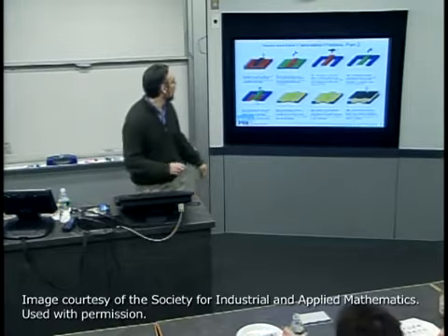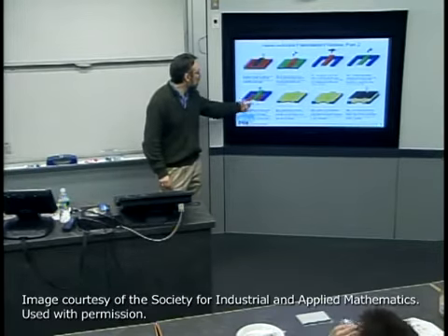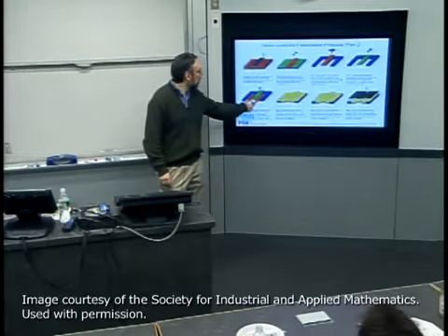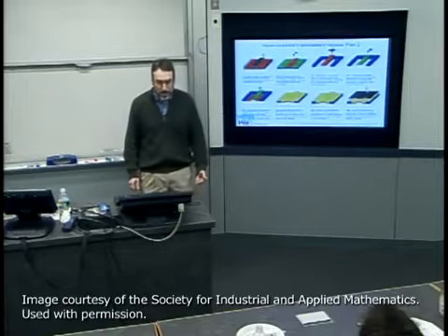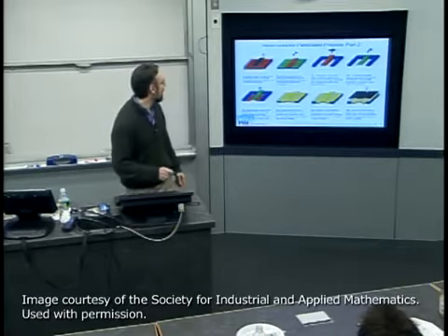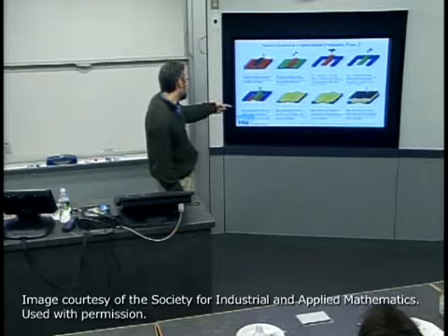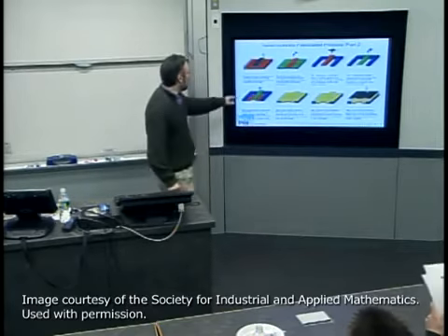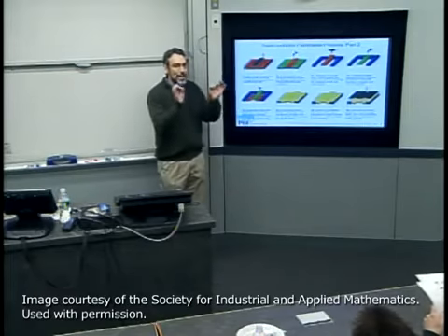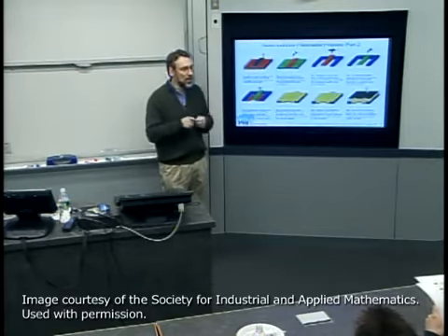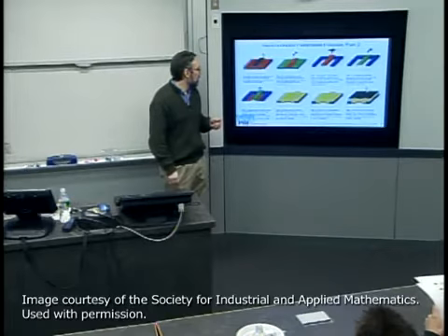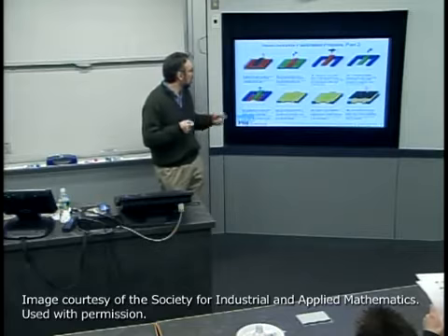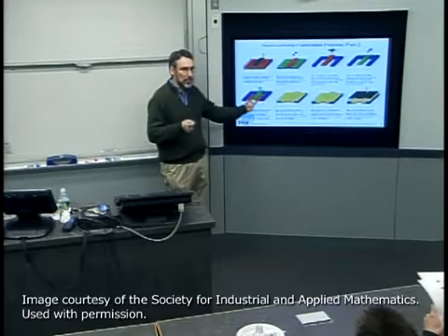Going on, the next thing we need to do is start to form these source and drain regions. We need to differentiate the silicon underneath. And what we're going to do here is use another process, an ion implantation process, I believe. Yes, I think that's what their little picture there is, where we actually implant those dopant atoms. We shoot them with essentially a high energy electron gun or ion gun into the silicon in a very controlled fashion.